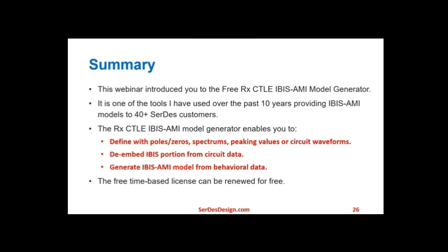It supports de-embedding the IBIS portion from the circuit data to obtain the AMI portion, and it supports generating a portable Rx IBIS-AMI model that can be used in any channel simulator. Its free time-based license can be renewed for free.